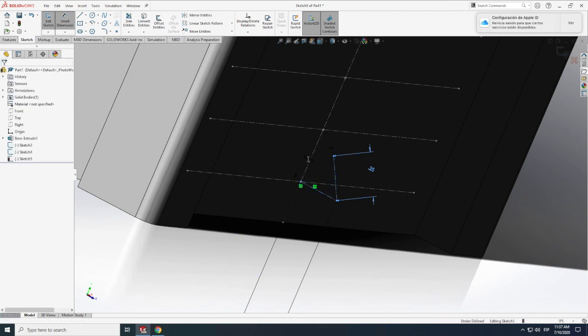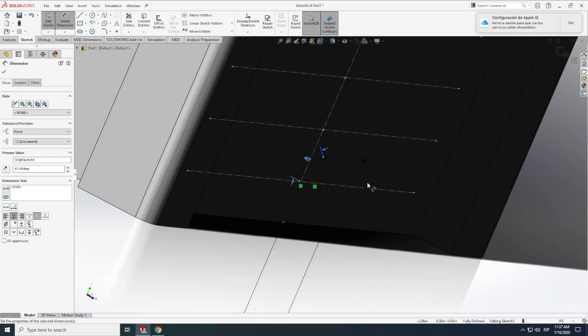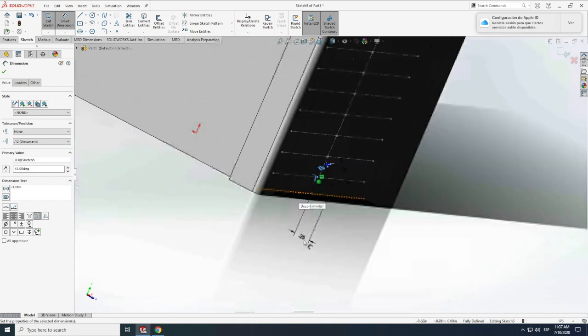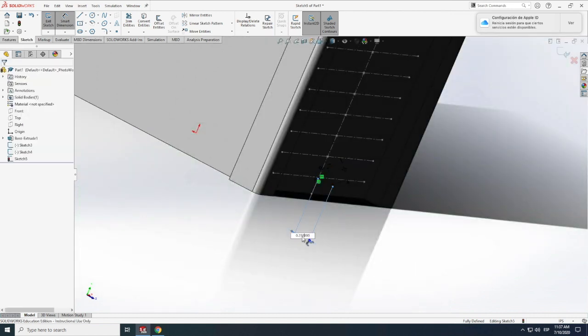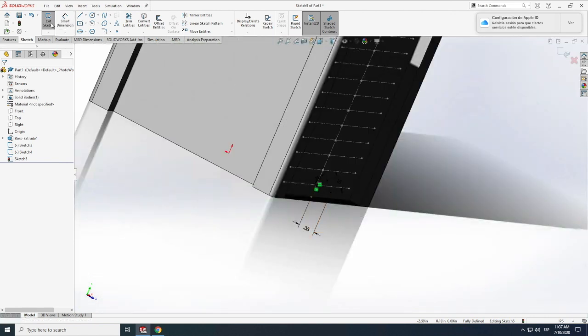And then we're gonna click in that line, we're gonna click in that line, and we're gonna specify an angle. So let that angle in there be, I don't know, 45 degrees. That is already beginning to look way better. I'll make this go a little bit farther out. Let's say 135. Just there we go. Just exit. Now I'm gonna exit the sketch. But now all we have is a line. So this is coming out from the plane in there.